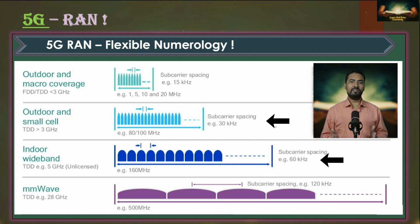Millimeter wave deployments, which offer extremely high bandwidths, require careful selection of subcarrier spacing. If you use a smaller subcarrier spacing in these high frequency bands, then the FFT, or fast Fourier transform, computations can be more complex and challenging. In addition, they also have smaller cell sizes, so a higher subcarrier spacing suits them better.